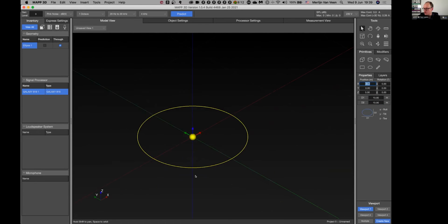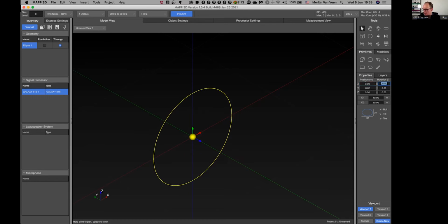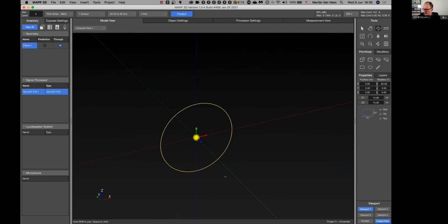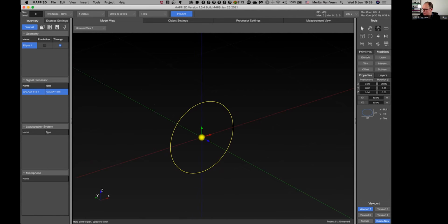And if I wanted to turn this into a sphere, I could use the same extrusion technique. But in order to do that, I would need to put the circle upright first. So I'm going to rotate it along the x axis. I'm going to roll it, and now my circle is upright. And now I'm going to use a different application of the extrusion tool. This time I'm going to use an angular extrusion of 180 degrees with a pivot point at xy equals 0. And what that will do is an angular extrusion and effectively turn my circle into a sphere.